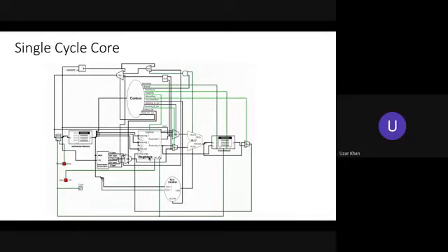As you can see, this is the implementation of a single-cycle RISC-V 32-bit I-type extension. So let's dive into it and see how the different modules of Logisim work. As we know, every processor has 5 stages, which include fetch, decode, execute, memory, and write back. As you can see in Logisim, we have the fetch stage. The fetch stage comprises a program counter, instruction memory, and an adder.